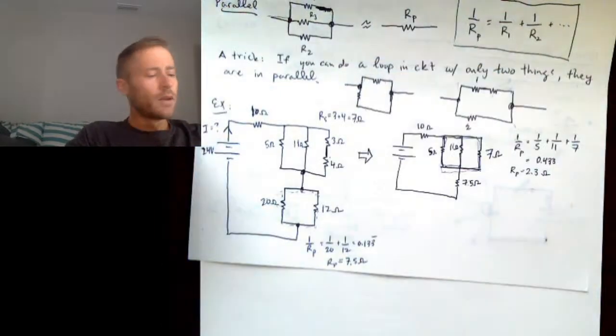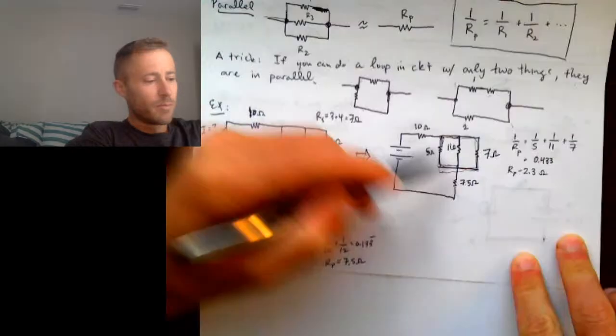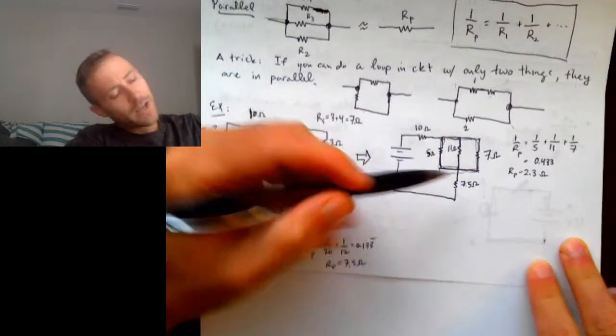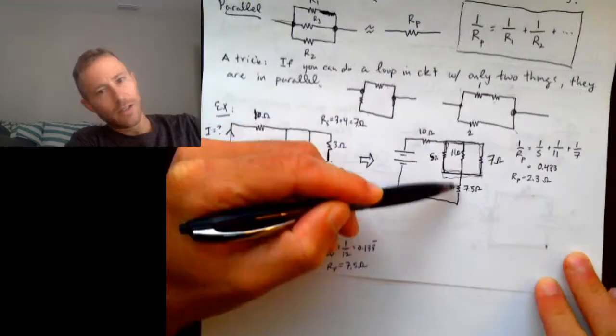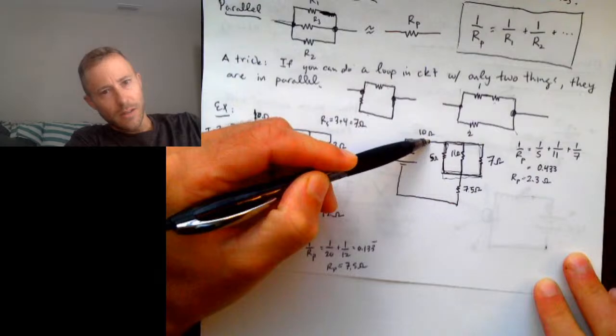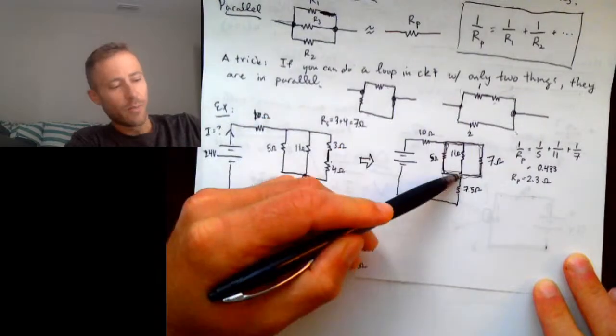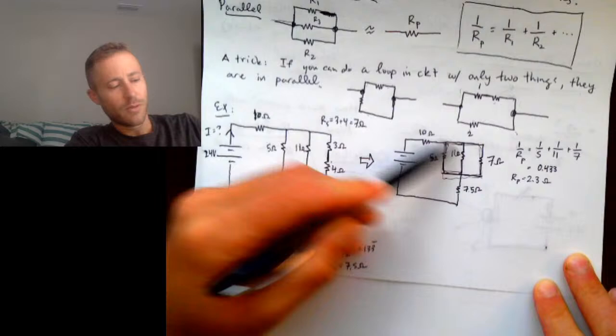And then the 7.5 is actually in series with the 10. Now, if I go from the 7.5 to the 10 in this direction, it wouldn't be in series, right? Because going from here to that location, the wire forks into 3 pieces. So there's forking if I go in this direction.